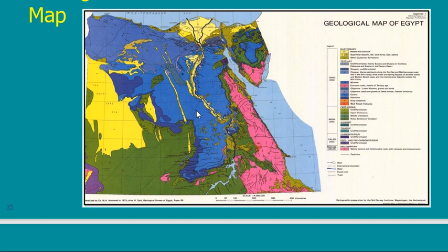But if the geologic map says that you expect to find sandstone, and I go there and find another type of igneous rock, so there is a difference. Then I have to increase the number of boreholes to check all locations, because maybe this is in just one spot, maybe in the other spot it is different. So it helped me to define the amount of investigation that I will need.